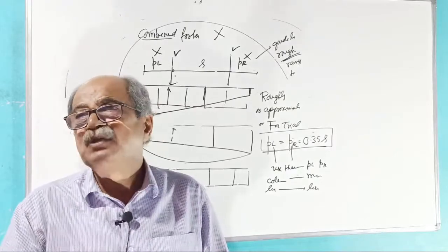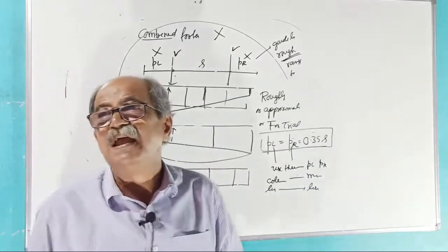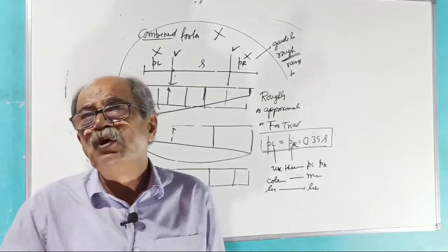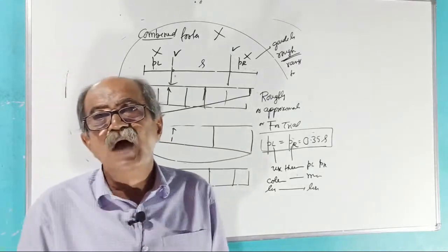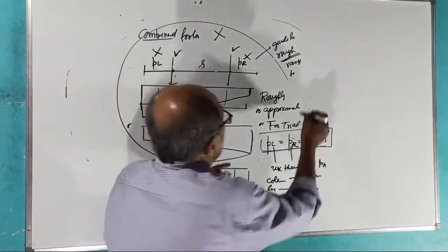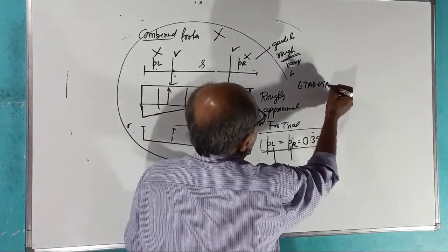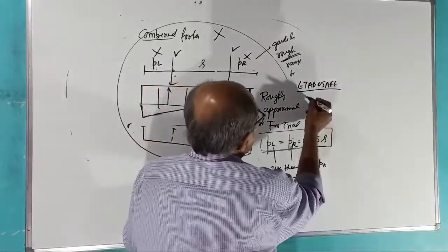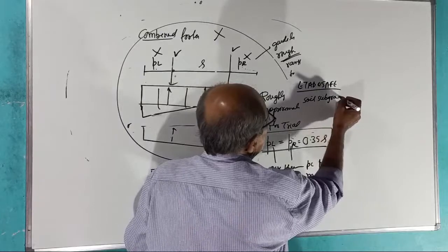See, actually we are considering here basic bending theory. We don't consider settlement of soil. But if you consider soil subgrade reaction, it is a very, very important term. When you go to ETABS and SAFE, when you create the model, it will ask you what is the soil subgrade reaction.